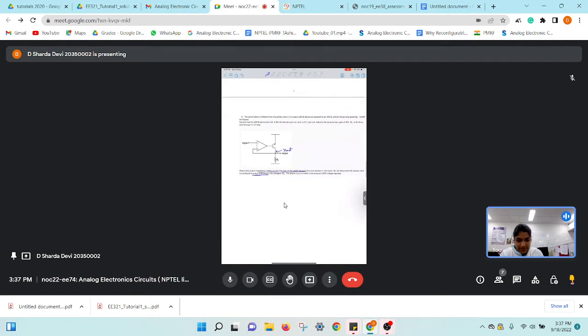Okay, so first things first. What is this particular terminal over here? This is gate. What is this terminal? Source. Yes, this is source and this is drain. You have to keep this in mind. And we also know for PMOS, our universal equation turns out to be Gm VSG plus GD VSD. This is the universal equation for PMOS, right? Your gm and r naught values will remain same.